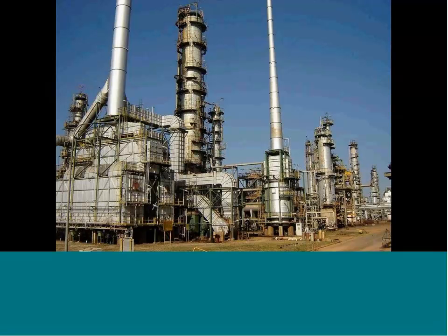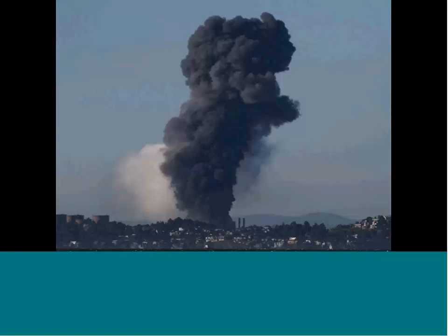And what we want to do at the design stage is figure out what can go wrong. So how bad could it be with your crude unit? Well, you could blow it up. You could have a fire or explosion within the unit. It happens relatively often in the world. Every couple of years, there's something in the news where there's been a major refinery fire or explosion, and it can often be in this unit. So what you want to do at the Hazop stage is identify how that can happen.